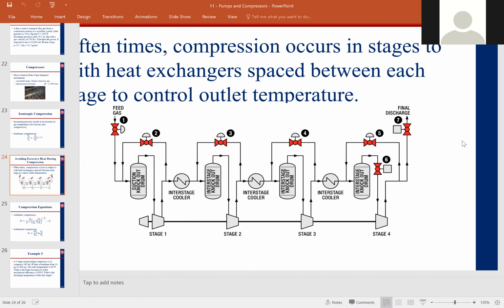The liquid's just going to hang out in the drum until it gets removed. Oh, okay. That makes sense. Yeah. So it's essentially existing as a phase separator, right? You're going to feed your mixture into it, but the liquid's not going to go up. It should settle into the drum. And so depending on how much liquid accumulates, you can just let it run until you do shutdown to drain whatever's left, or you have some sort of drain valve at the bottom of the drum that you open periodically.